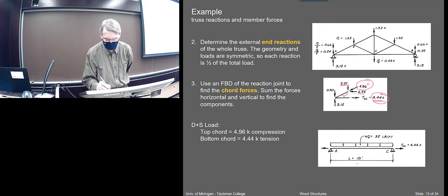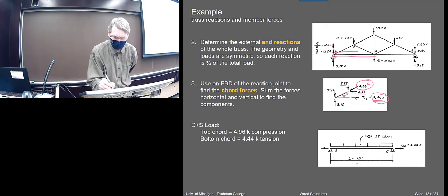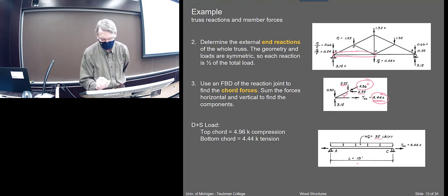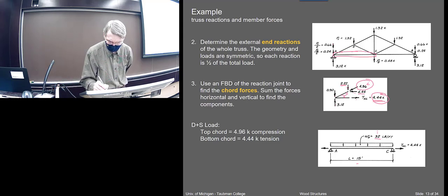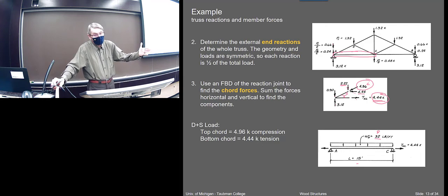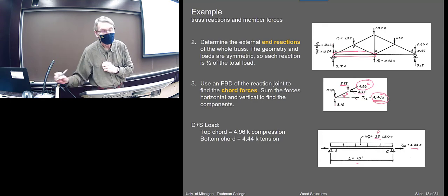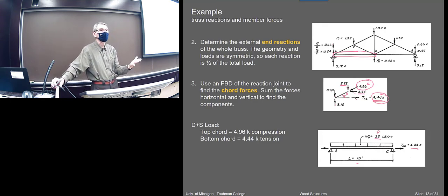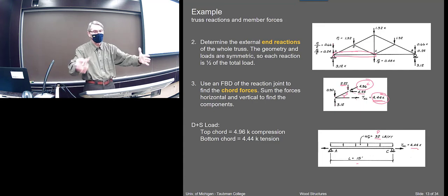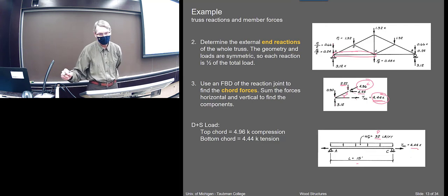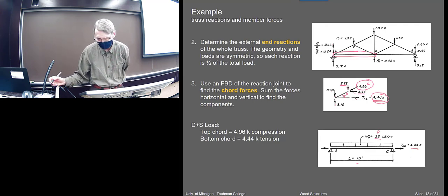Here's a diagram of the tension member. This is the bottom chord here, right? That guy has a flexure load on it. Actually, just the dead load is that 32. Although it only has the dead load on it in flexure, this load is coming from the snow load. So in terms of CD, I'm still going to stick with the snow load, which is what, 1.15 or something like that. The whole problem has the snow load on it, so that's going to be my CD for everything, based on the snow load.